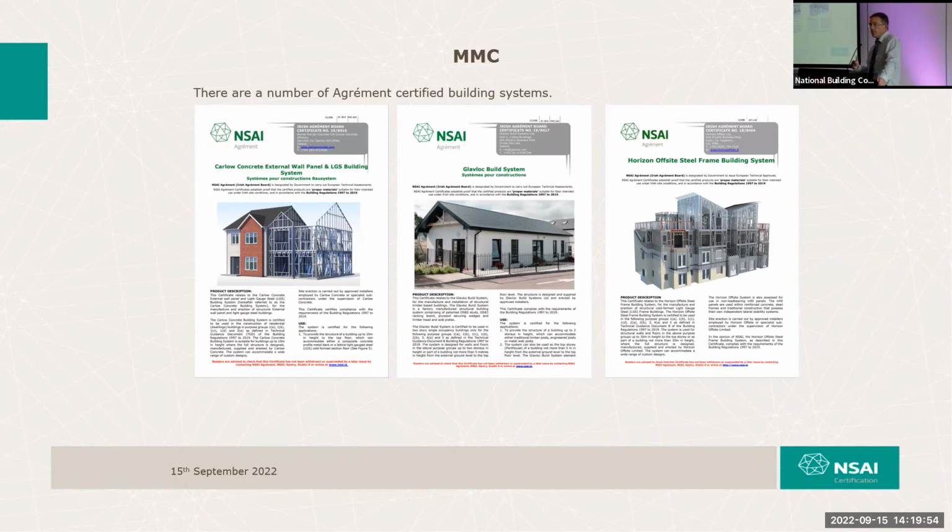It has to form part and parcel of the earlier design stages, because there's going to be a design process with your thermal modeler. There's going to be an over and back. Look, if we put a bit of insulation here, if we up the size of that insulation there, we're only, in fact, putting in an extra 20 mil of insulation, say, around the perimeter of the wall, but we're incorporating maybe a layer or two of thermal blocks there, and we're actually improving this junction fourfold. And it's not a fourfold uplift in cost, you know? So it's an over and back process to get things right.